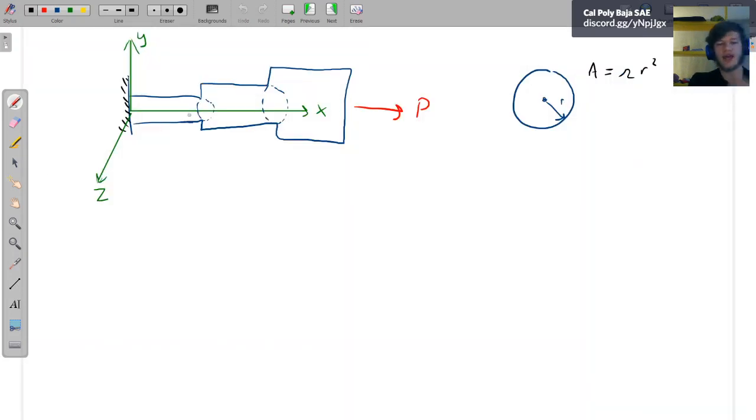All right, so we have our body. We now have a coordinate system. We just need to draw our reactions. So we have one force in the x direction, none in the y, none in the z. So we know it doesn't have to resist either of those to be considered static, because at the end of the day, this is still a statics problem. This thing isn't moving.